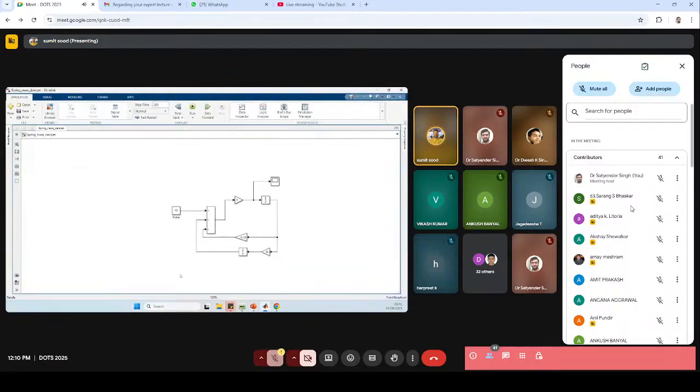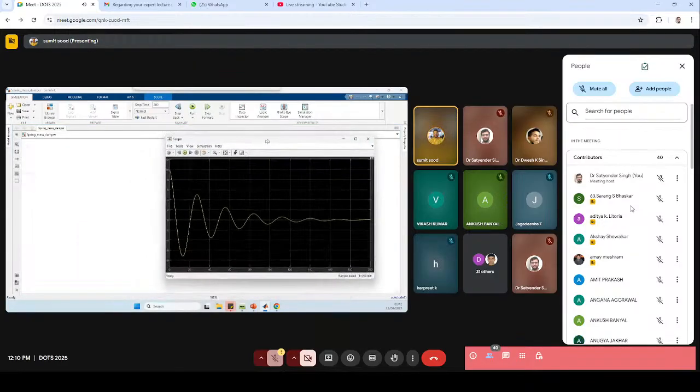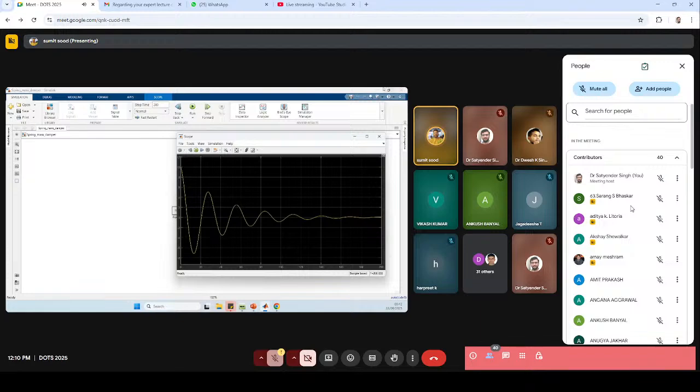You can see here the same model developed in MATLAB Simulink. You can use this representation. This is the summation block. This is the source of effort. This represents the integration of the I element. This represents the damper, and this represents the compliance element, or the spring. If we run this system, it should give us the same results. So let's see if we get the same displacement. You can see here that it gives us the same effect.